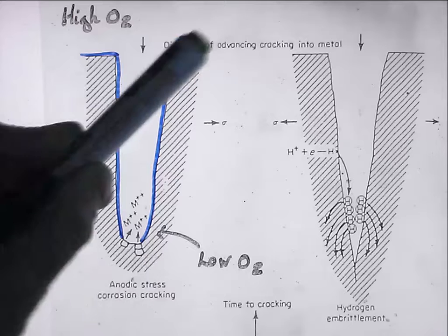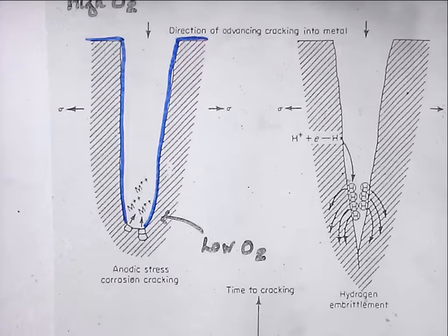The case on the other side we'll come back to is hydrogen embrittlement, but this diagram's quite nice in that it does actually illustrate on the bottom that for stress corrosion, and indeed for corrosion fatigue, and all our other localized corrosion mechanisms, we need an anodic current flowing in the material.